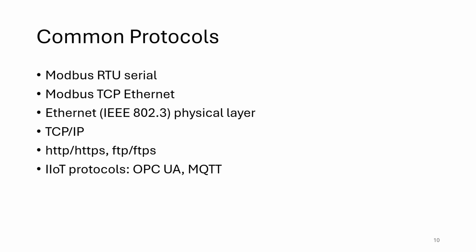For example, industrial Internet of Things protocols include OPC-UA for sending data with lots of context, and MQTT, which sends simpler messages, which typically include an identifier and the actual data packet itself. And often with the MQTT protocol in particular, you then need to add some additional context on top of the data. So there's a variety of different layers at which the data can be sent, ranging from the bit or byte layer all the way up to an actual defined message that can be read and understood and interpreted by the machine or even by the people who need that data.